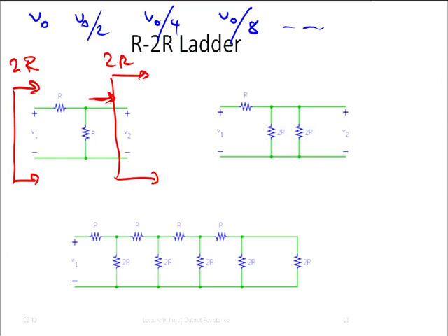If we simply connect the same one, then instead of having resistance R here, we have R in parallel with 2R. So how can we fix that? Well, we can break up this resistor R that's shown here. What did we do with R? We made 2 resistors of value 2R. What does this behave like? One resistor with value R, right?